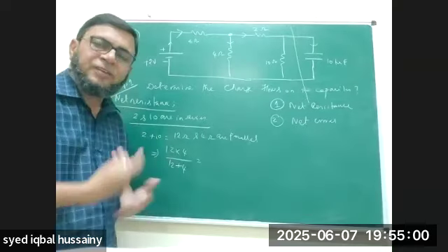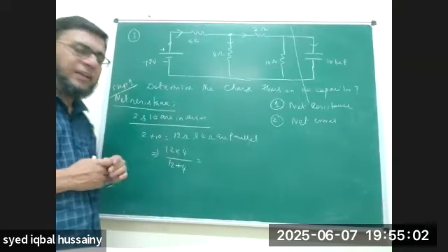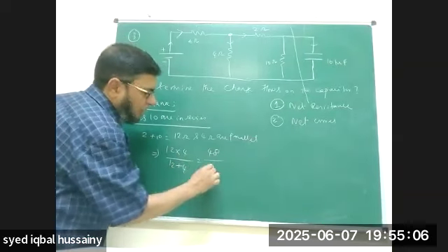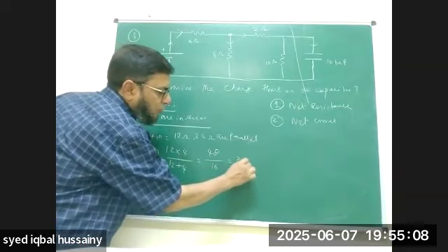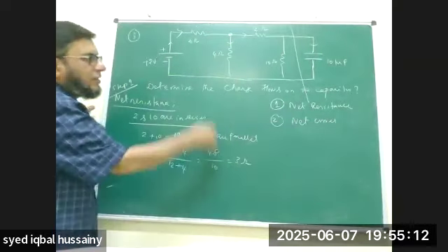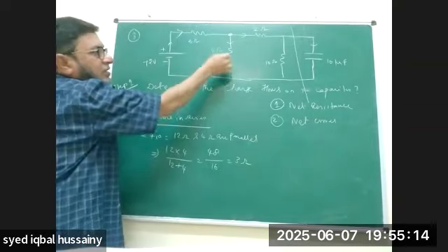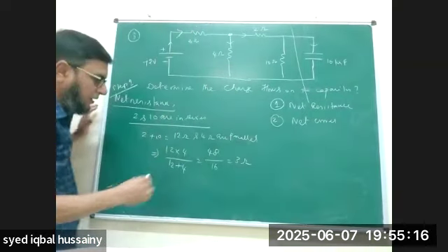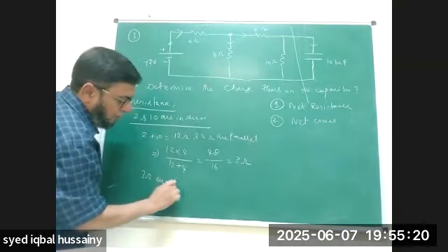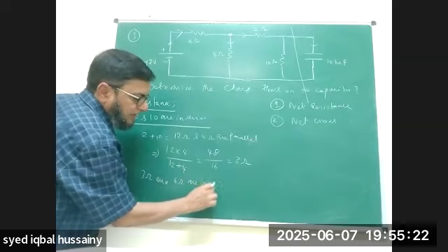तो शॉर्ट ट्रिक फटाफट करके जाना है, क्योंकि लेंथी न्यूमेरिकल्स होता है ना, तो जल्दी करना है. तो 12 into 4 48, 12 plus 4 16. तो इसका 3 ohm. Okay, so this 12 and this 4, I solved that. 3 ohm I get. Then this 3, this answer and this 6 ohm is series. So the answer 3 ohm and here 6 ohm are in series.